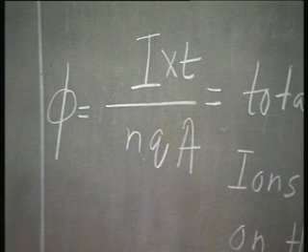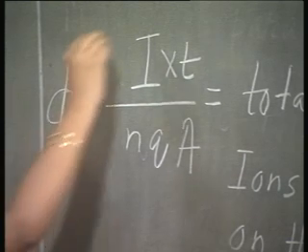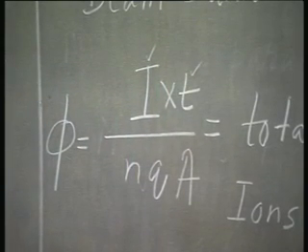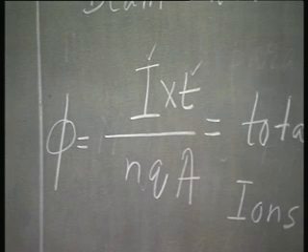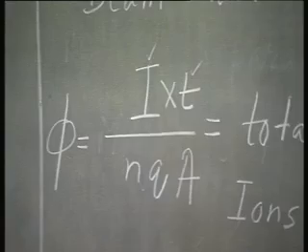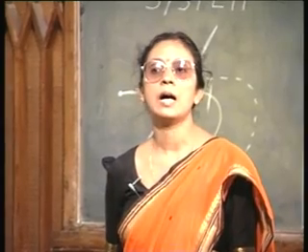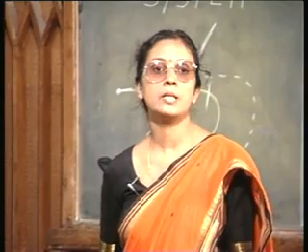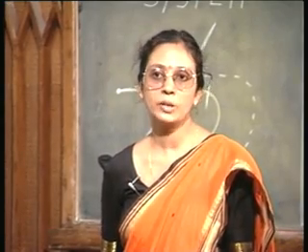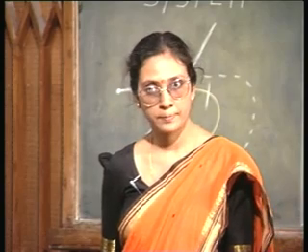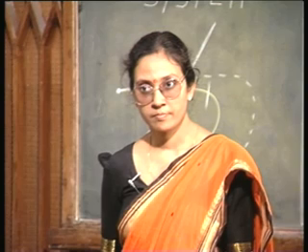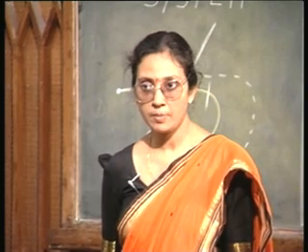So, you see, you can control the dose either by controlling I or by controlling t or by controlling them together. So, for a practical system, what would you want? You would want a high beam current, right? If you have a high beam current, then you can impart a large dose within a relatively short time. Agreed? t can be made small.